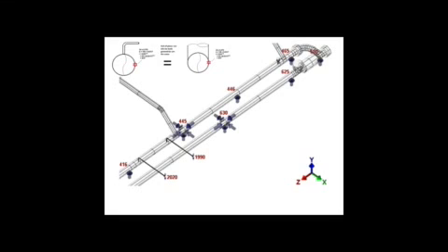So it's putting a bending moment about the main header pipe. It could potentially overstress the main header pipe in a completely artificial way due to the SIF from the pipe that's attached at 1990. In addition, there's very little flexibility in that small piping branch, so when this large horizontal run moves the large header, we're going to crush that small pipe. So in those cases, it's very important to evaluate the flexibilities and the SIFs where the small pipe is attached to the big pipe, so that we recognize where we've got real stress problems and artificial ones.